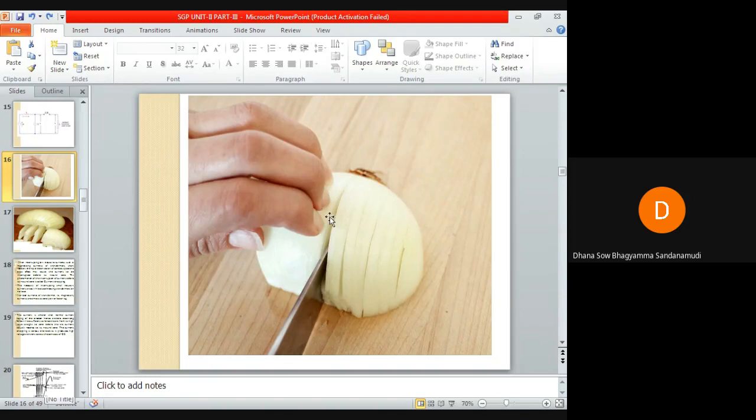the current is suddenly going to zero at this particular instant where the person is chopping. So instead of interrupting the current at this current zero edge of this loop of current, it is being interrupted somewhere within the loop. For example, a person is chopping here, so let us assume the current has suddenly fallen from its maximum value to zero here.